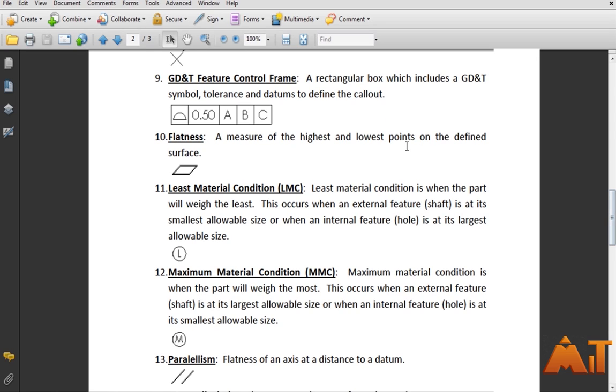When you're manufacturing parts, because parts are very complex, there may be different places, when you make a fixture to put it into, that it has to rest on. A datum target would be another area that it's going to be resting on. You'd define a certain surface that would rest on it. It's not a datum feature, but it's an area that it's going to be resting on in your fixture.